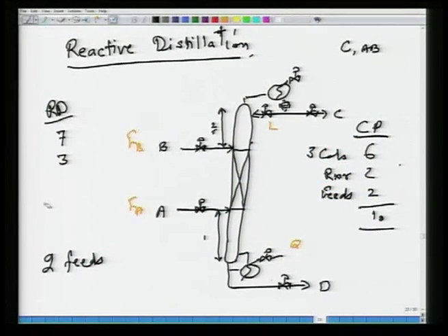Okay, and this 4 is also a misnomer, it is actually 3, because 1 mole of A reacts with 1 mole of B, and if you are not allowing any A and B to leave the system, if you are setting FA to be 100 kilomoles per hour, well, FB has to be 100 kilomoles per hour. So, actually degrees of freedom is only 3. Okay, so I think the degrees of freedom here are wrong. 1 requires FA equal to FB, that is something that is dictated by the stoichiometry of the reaction. So, degrees of freedom is actually only 3.